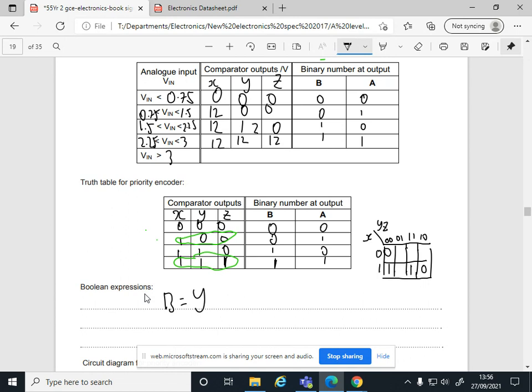Don't cares mean you can group them, you don't have to group them. So X, X, X, and X. Don't cares. Okay, so I can see 2 groups of 2. I think those are the best ones I can see there. So you can go for this one. It's a group of 2. So A equals X and not Y. Okay, that one, X and not Y.